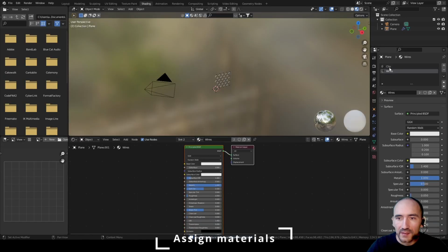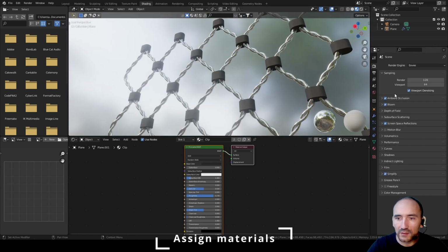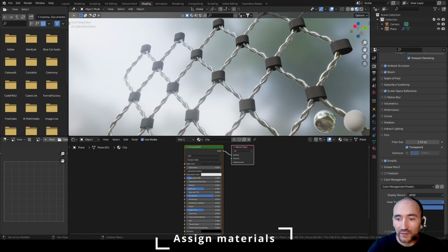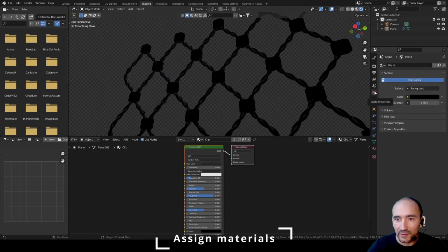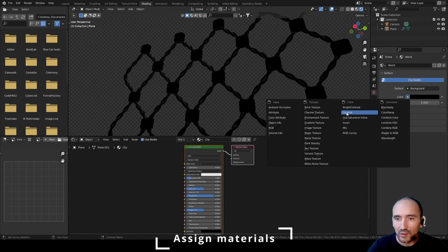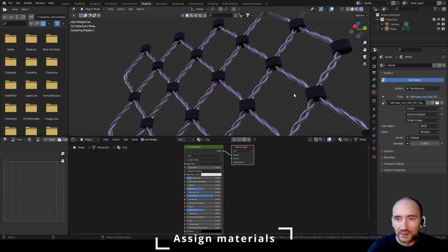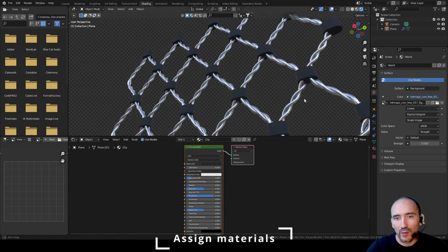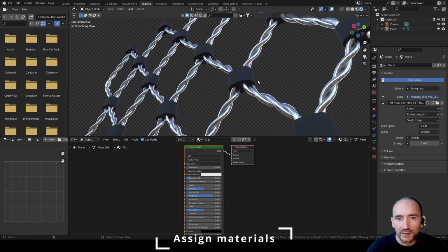Go to shading and select the clip material, check the EEVEE render engine, go to film, make it transparent, color management, not filmic but standard for this tutorial. Click here to see the final result of the image. Click the world properties, set the color and environment texture, open the image, select the HDR you want, set 3 for the strength so we can see a better strength of this environment image.